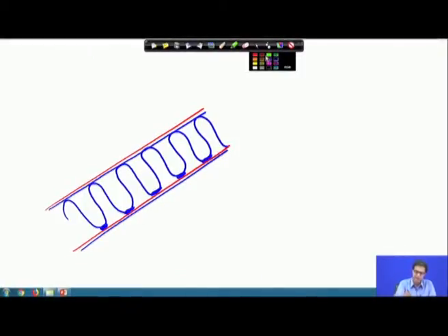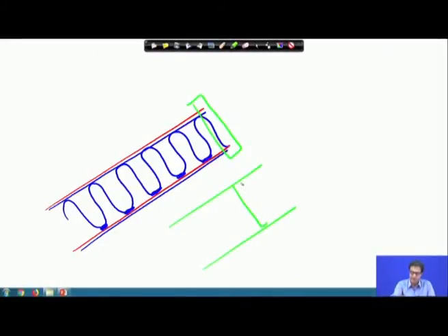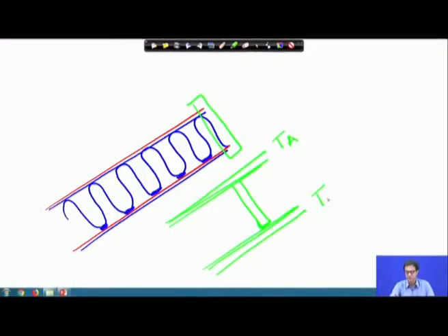So, now if we look into it carefully, what we have is basically a separating wall, and each individual layer we can think of as a fin connected between the two separating plates. So, what we need to analyze finally is a plate at temperature T A and another plate at temperature T B, depending on the type of fluid, two plates connected by a separating fin.